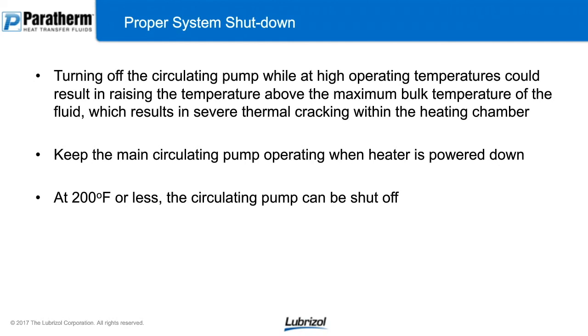So imagine you have a fluid flowing through your heater coil out into the system, and all of a sudden you just decide to turn the circulating pump off at the same time you turn your heater off. But now your fluid is sitting stagnant, not removing any of that heat energy that's built up in that heater chamber. And you're just going to be cooking the fluid right on there. It's kind of the equivalent of cooking something on a stove top and leaving it sit there under high fire and not stirring it. You're basically just having it sit there and take all that heat energy in to break the fluid apart.